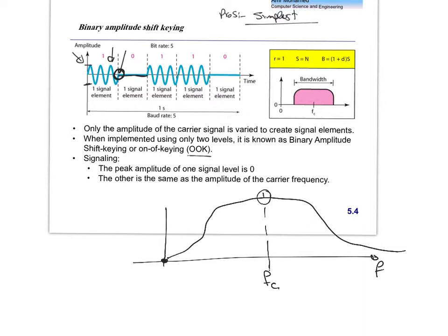So that's the same problem that we had in digital communication, right? Except that here, because of using the sine wave, the highest power exists around the carrier frequency. So we cannot transfer a signal like this over a bandpass transmission medium as is. So at the sender side, we have to use some kind of filter, so that we can approximate these parts and send a clean bandpass signal over the bandpass channel. Okay, so depending on this filter, we calculate the value of D.